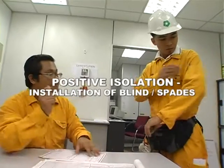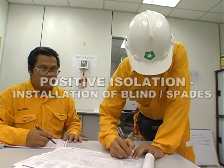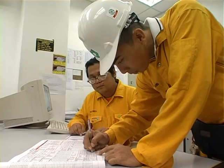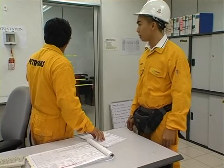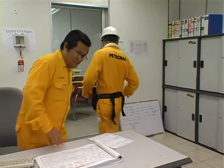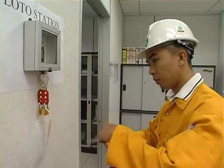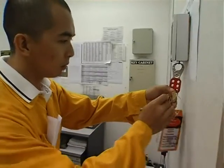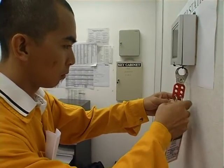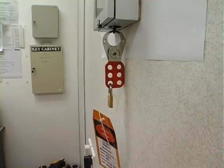In cases where positive isolations are required, a separate PTW must be applied for the job. Before installation of blind or spades, RA must place his department lock and personal brown tag at the lockout box. After completion of the job, RA must remove department lock and personal brown tag from the lockout box.